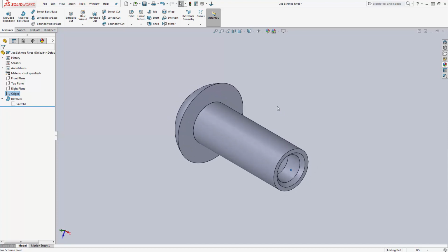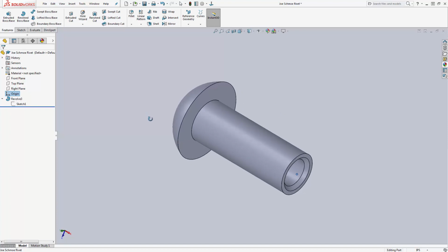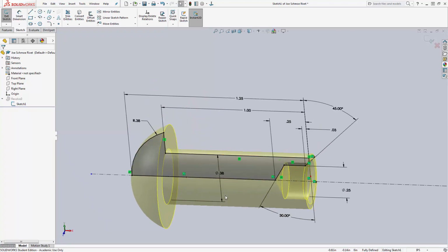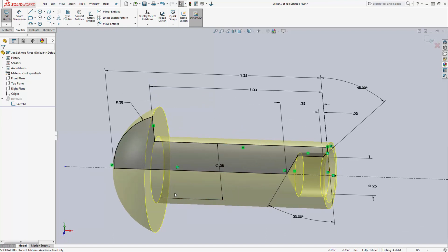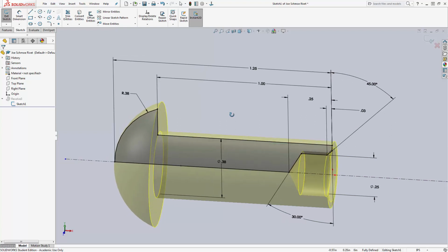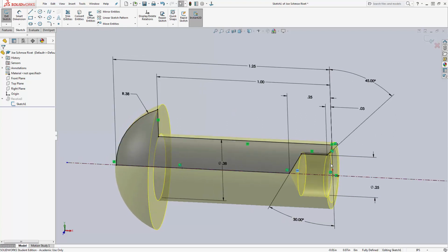Okay, so in this video, we introduced a little bit of sketching, and we talked about the revolve. And when we went to the sketch, we focused on thinking about the geometry to begin with, about putting a center line through the origin, where the origin should be, and then we did the sketch. Now, we didn't even bother with the dimensions until we got our relations all set up and made sure that they were all good. But we saw that our sketch was all blue, and even with the relations, most of them were still blue.